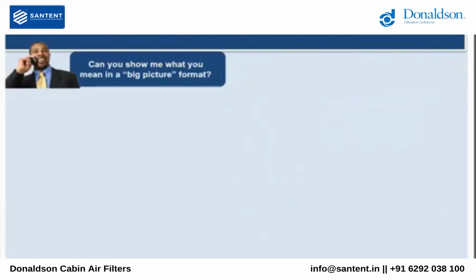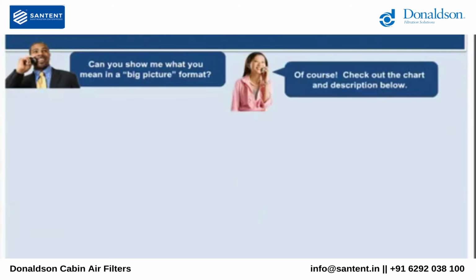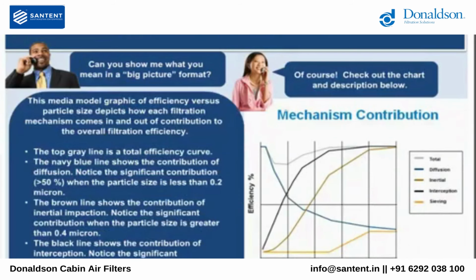Can you show me what you mean in a big picture format? Of course, check out the chart and description below. This media model graphic of efficiency versus particle size depicts how each filtration mechanism comes in and out of contribution to the overall filtration efficiency.